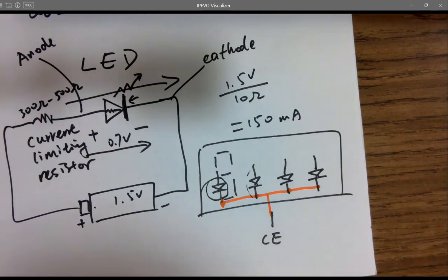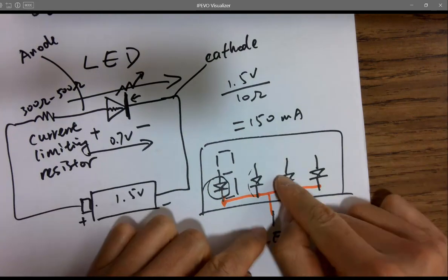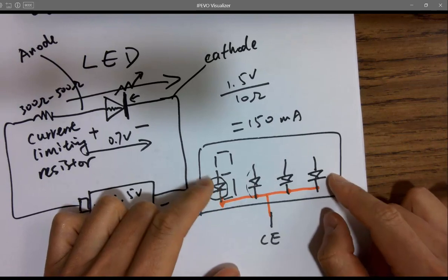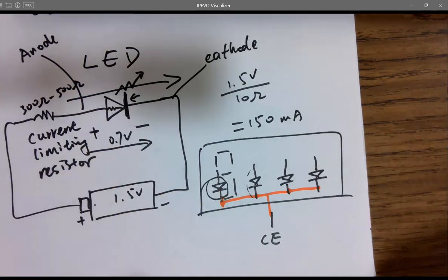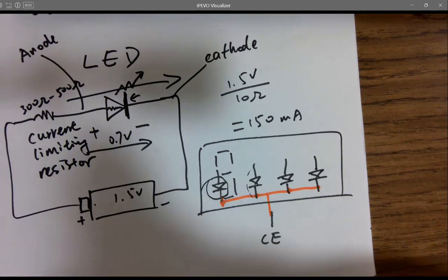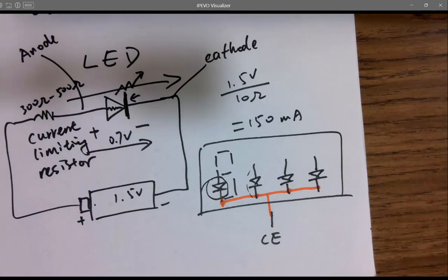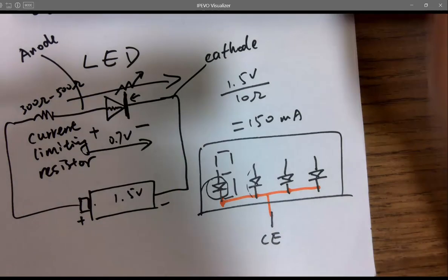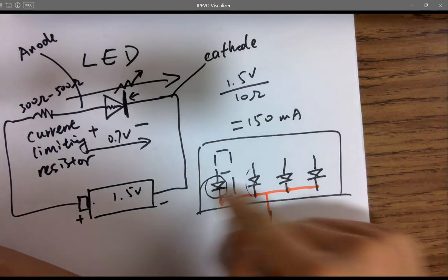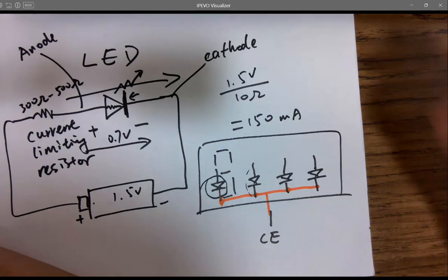So what's the consequence of it? If you turn on that LED, all the E's will be on at the same time. But you have 4 modules. How do you want to display different things on it? What's going to happen? How could you program it or manipulate it to show different digits or numbers on the four display units? Because whenever this is on, all the E's are on. It's the same for the other LEDs, right? If you turn it on, all of them are on. It's going to show the same number.